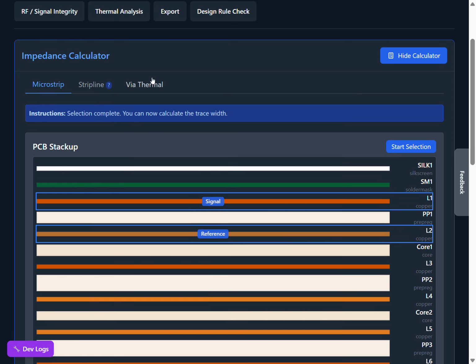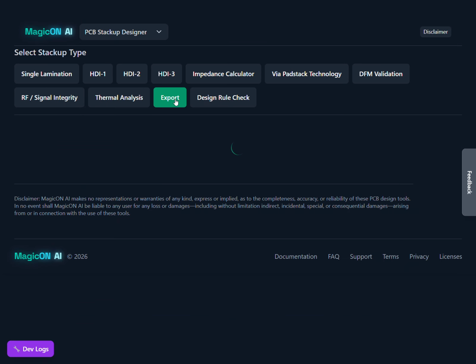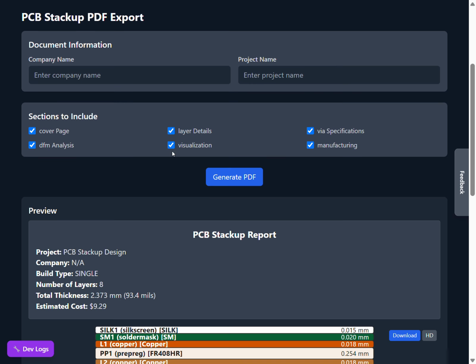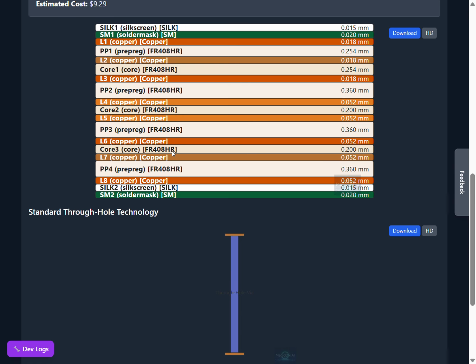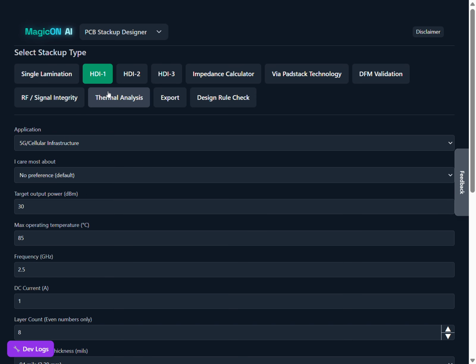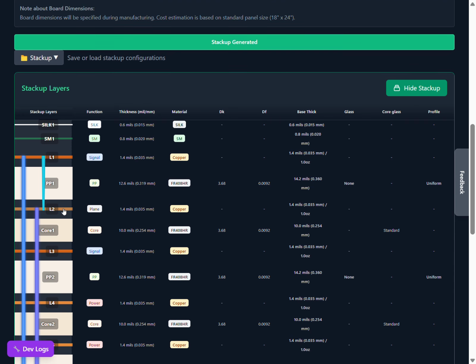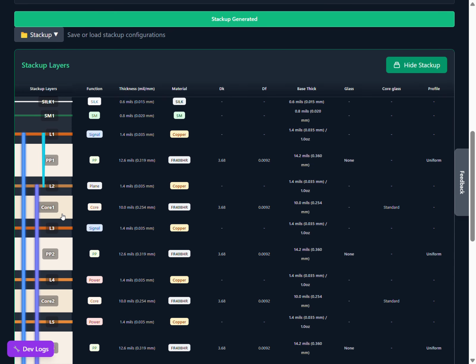When to choose: use microstrip when you need easy access, can have lower conductor loss in many cases, geometry and frequency matter, or your board is mostly 2 to 4 layers. Use stripline when you need EMI control, you're mixing RF with sensitive analog or digital, or you're routing on inner layers by design. In real boards, vias and layer transitions matter just as much as the line type, and microstrip to stripline transitions need proper via design.